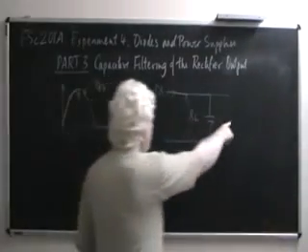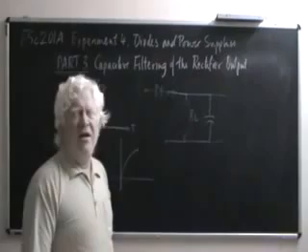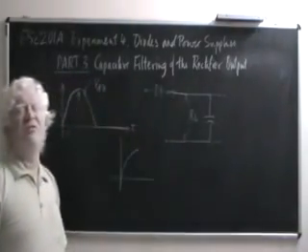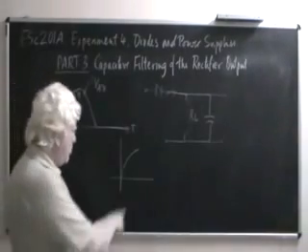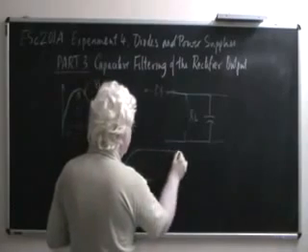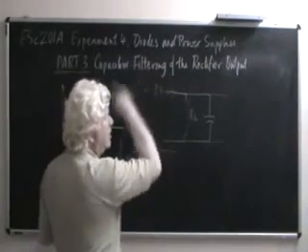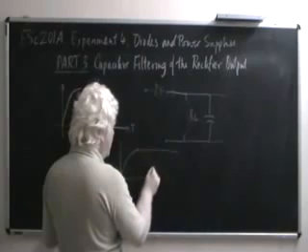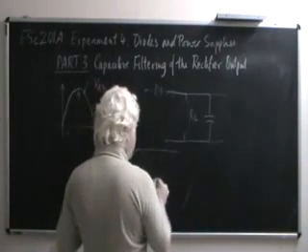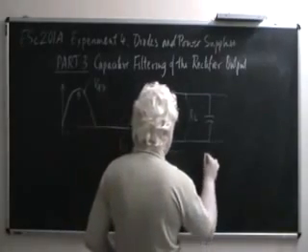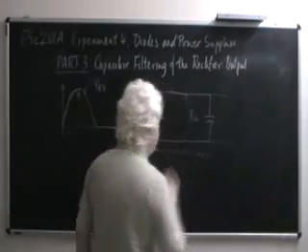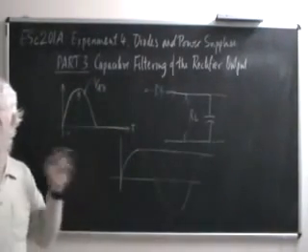The output, under ideal conditions, when there is no resistor and when the diode's reverse resistance is infinity, would follow this up to this point and then would remain flat. Whereas the input to the rectifier has gone down, gone negative, gone up again, gone positive again. This just remains flat forever and ever under ideal conditions.